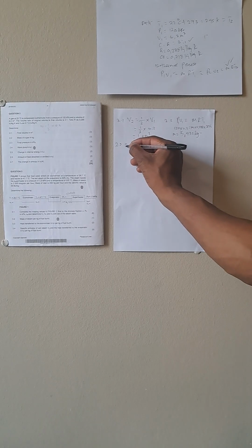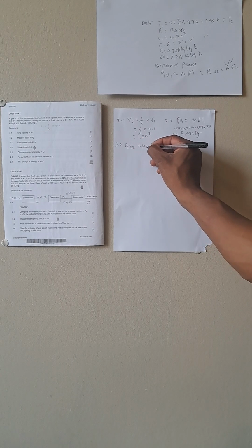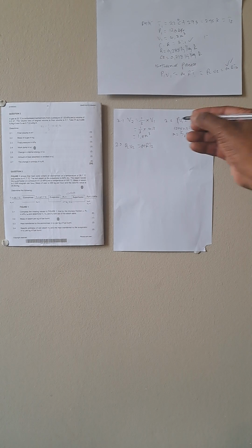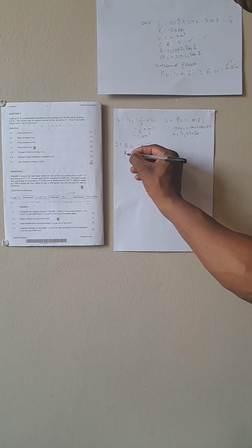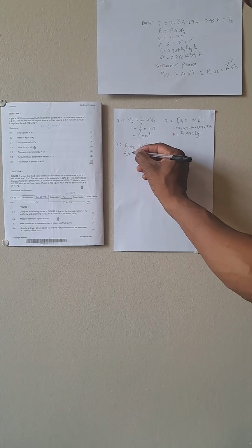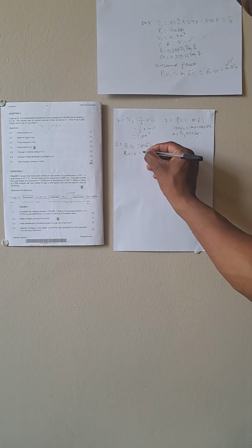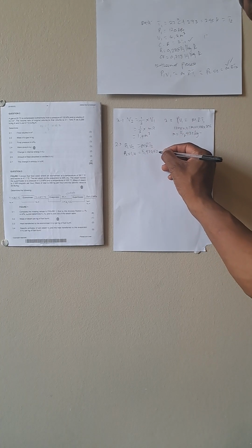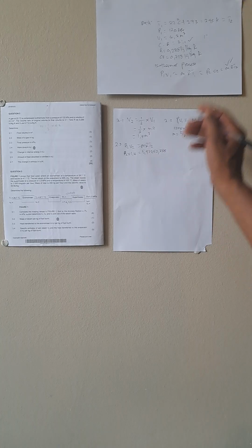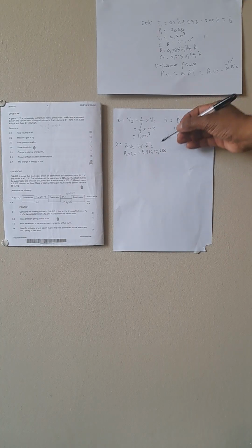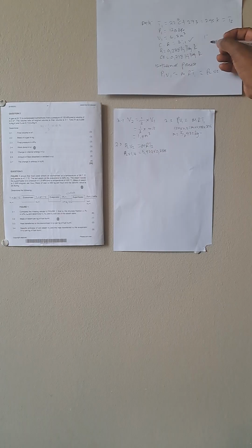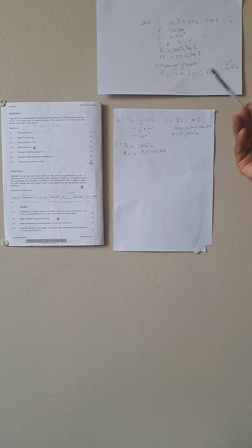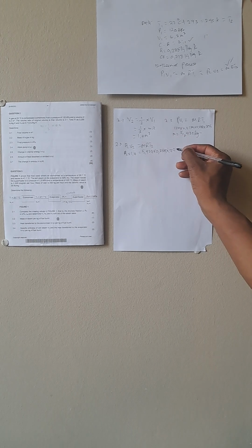So we can use our formula P2 V2 equals MRT2. Do we have our P2? No, we are looking for P2. Our V2, yes, we just calculated it, it's 1.4. Our mass is 5.932, times our gas constant 0.288. And don't forget, this is an isothermal process, so our T1 is equal to our T2, which is 295.